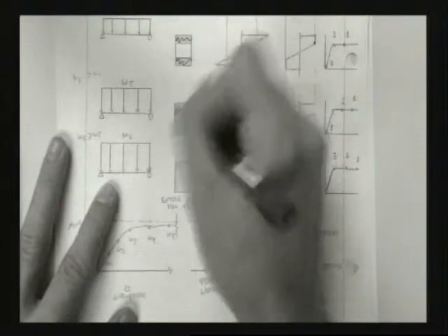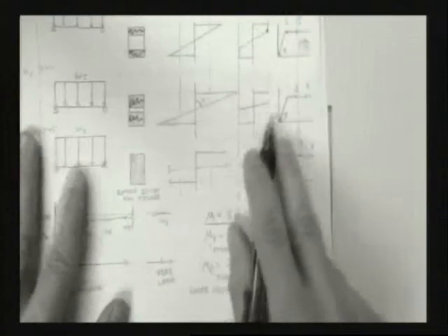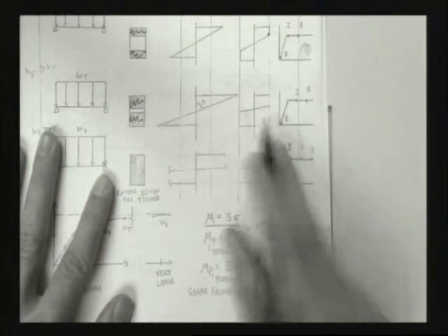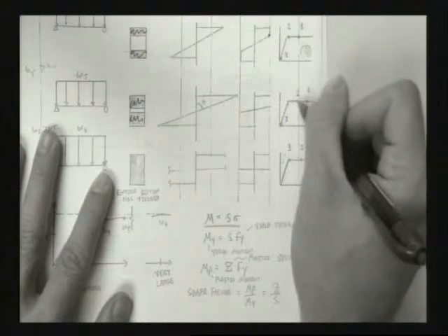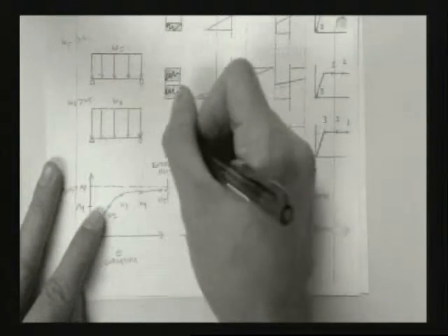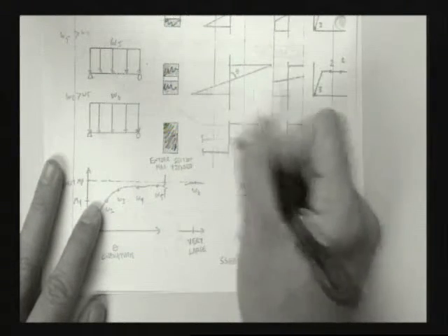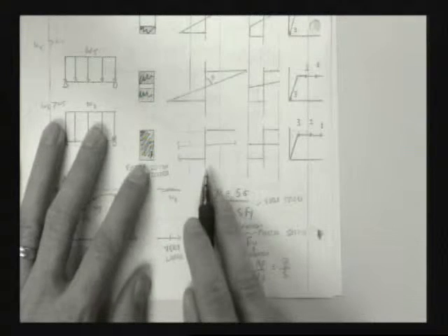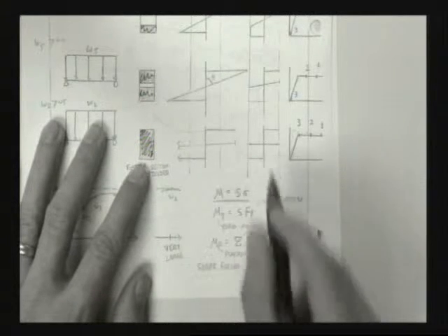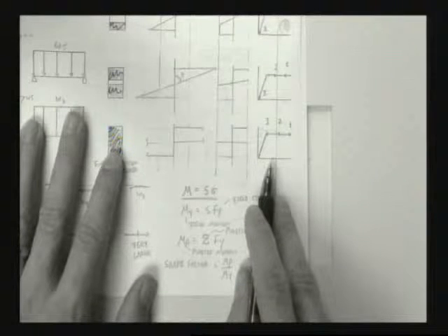Keep increasing. Now all of this is yielded. This is what our strain looks like. This is what our stress looks like. Well, we're getting pretty bad now. It's getting pretty high up on the hill, but it's not dead yet until the entire cross section is at yield. Everything is at its yield strain, at its rotation. Everything is at its yield stress. Boom, something like that.